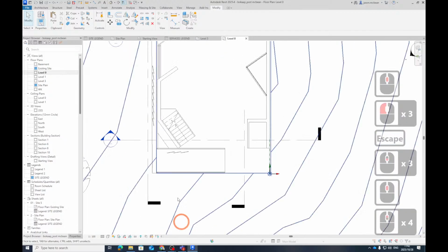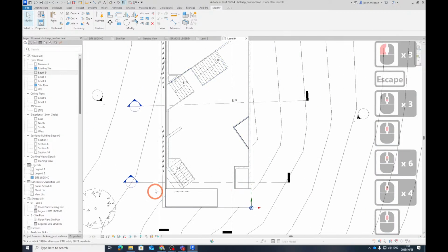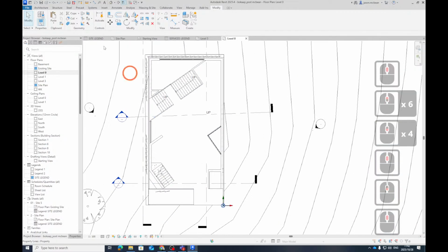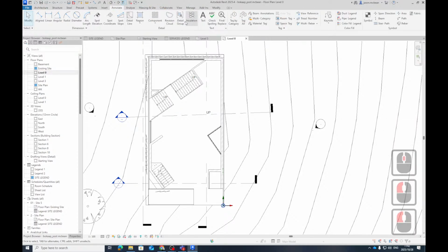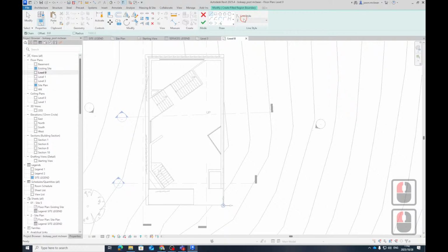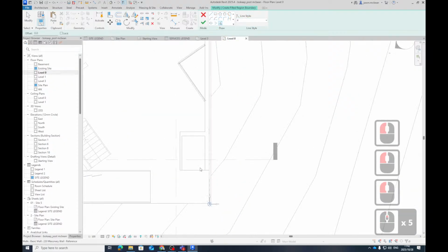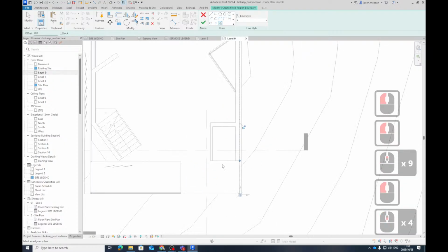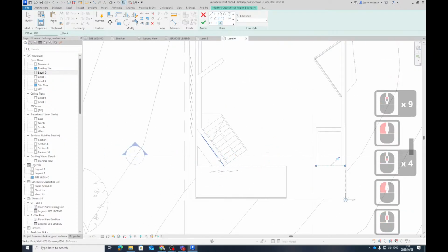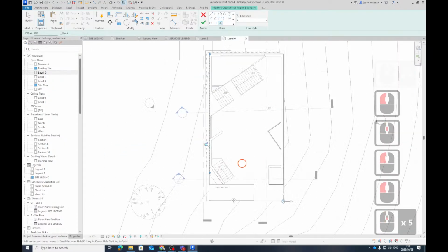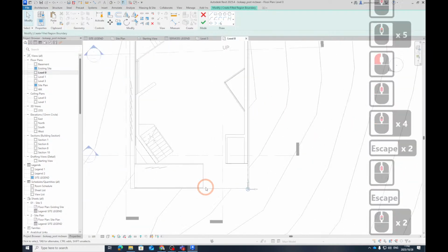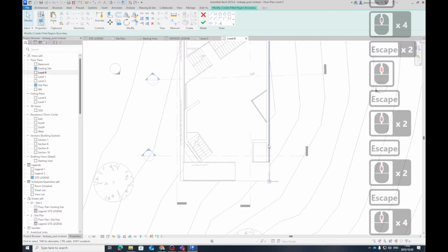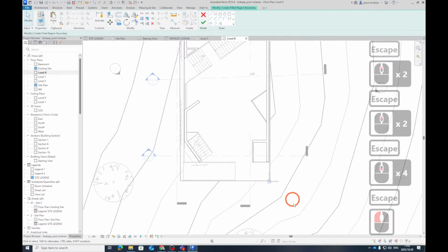So watch this. So say now, this is the extent of your building. You're going to go to annotate, again, drafted annotation. This is quite a thickish line, again. This will be like line weight 4 or 5, 4. Pick line. So I'm going to say I want that line, because maybe this is the only extent of your building. This is the measurable area of your building. That facade detail doesn't factor. So I'm going to isolate or switch on your line weight so I can see the line weights a bit.